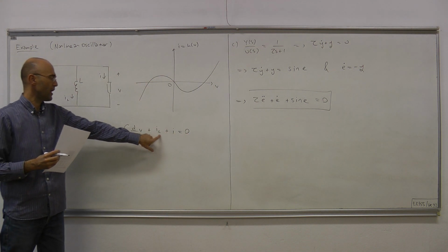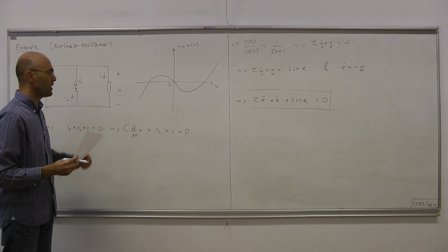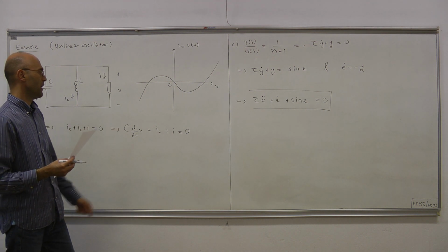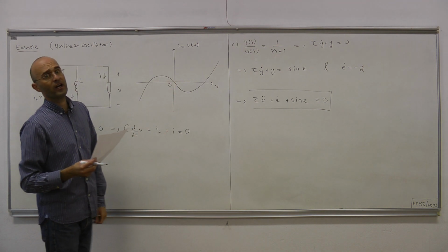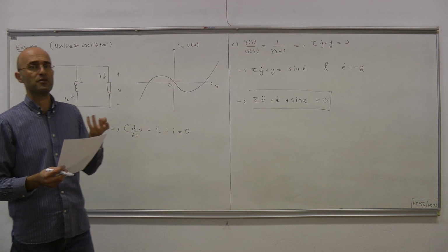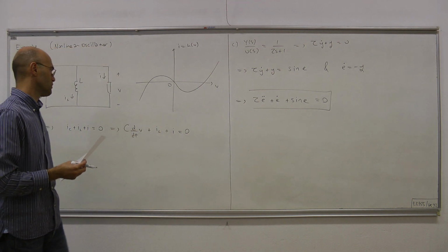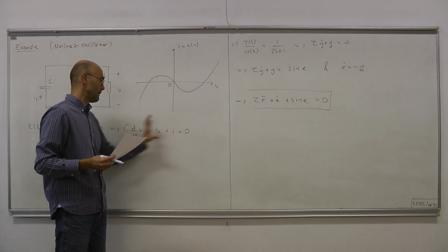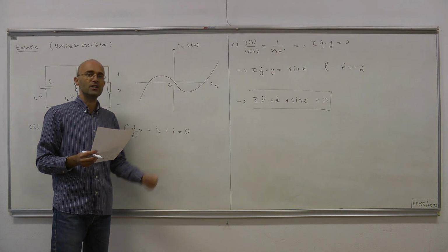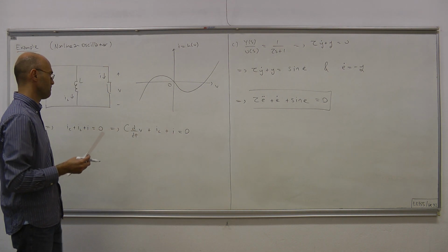We didn't touch IL and I at this point. Let's differentiate it once again so that we have the derivative of IL. Why do we want the derivative of IL? Because once we have the derivative, we can express it in terms of voltage. And that's pretty much what we want to do. We want to be able to express this equation only in terms of the voltage.